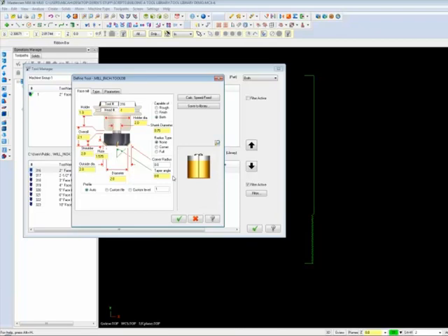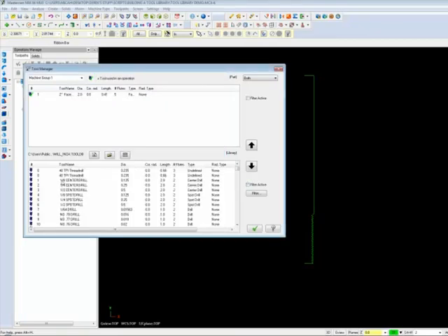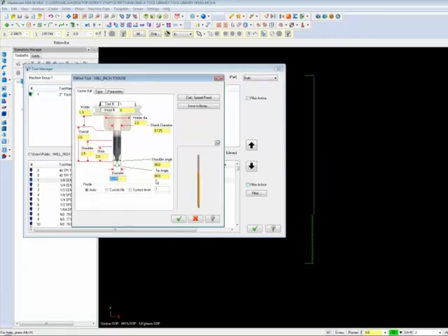Yeah, you know what that is, Jay, I think years ago we used to be able to put 90 in there, those of us who've been around for a while. But I think Micah has just identified either the workaround for that or the way it's actually supposed to be defined. Right, that's fantastic. Except, Micah, try to put the corner radius on the tool. That's the issue. Yeah, that's why I didn't put a corner radius on it. That's why a lot of people just use a bull mill and be done with it.